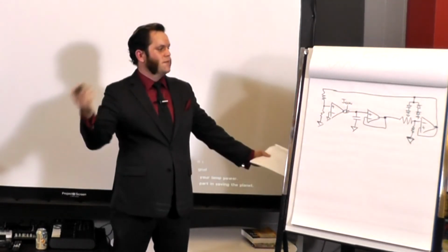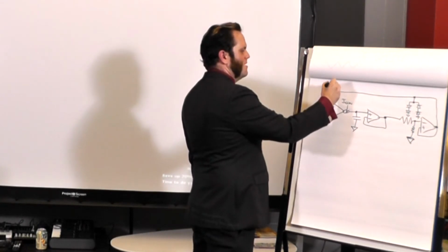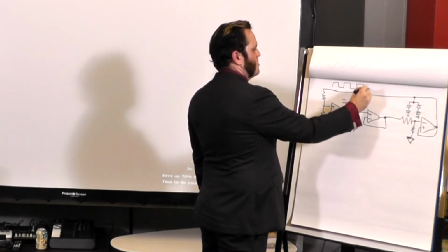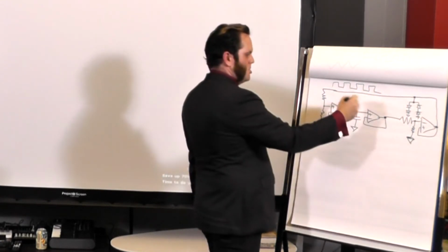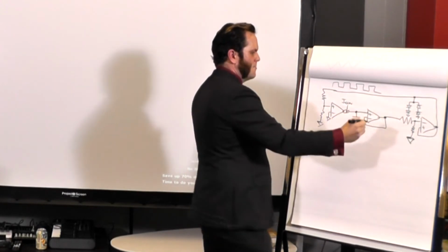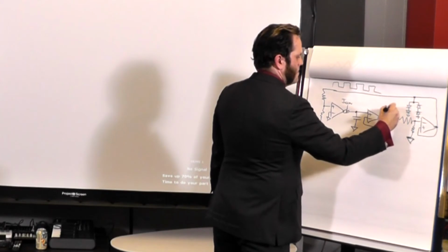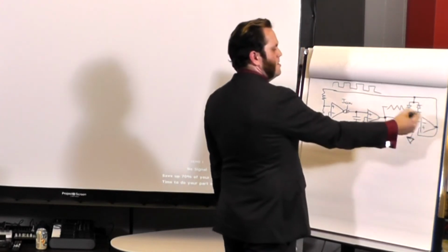So what this guy is doing is we have our voltage input here. Hey, look, it's toggling between plus and minus 1.4 volts. This is our plus or minus V in source. And that basically is changing the direction of this integration right here, and we can tap off on this side of the buffer if we feel so inclined. And that gives us a nice triangle wave right there, which is then going to this OTA.